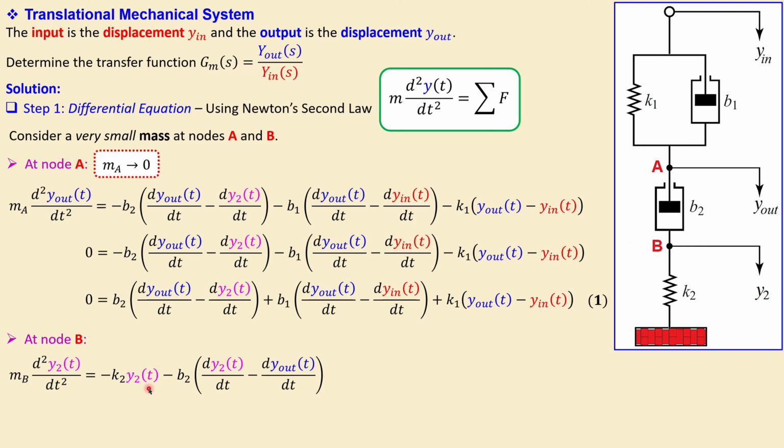That's actually shown here. And again a minus sign to fight that back because it's fighting back, and minus B2, it's also fighting back. In this case the Y2 is only displacement here because this is a mechanical reference point, so it is just 0. So that's the minus K2 Y2 and a minus B2, and again the difference between the motion here and the motion there. And since we consider now B2 here, this is what we take first minus that velocity there.